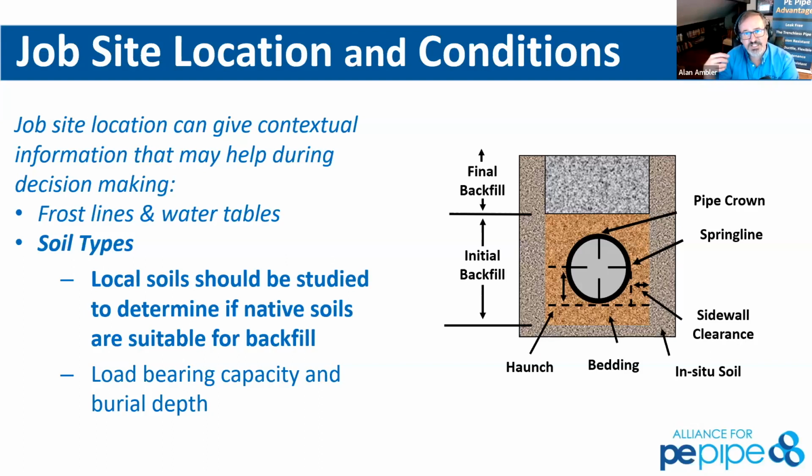We want to know about that changed condition. And that enlarging of the borehole that Dan had mentioned earlier, where it's about 50% larger than the actual pipe itself, is going to help ensure that we remove any dangerous material for the production pipe as we pull that through.